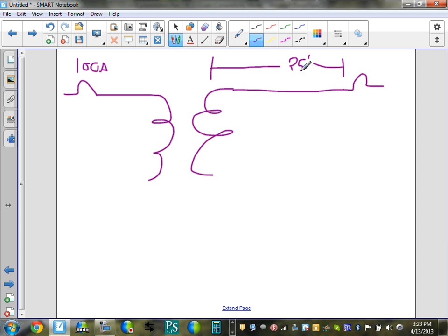The rules are to size it. This conductor is going to be, let's start with 1/3 this time. 1/3 multiplied by the overcurrent protection device, which is 100. Our voltage is the same thing, 480, and 240 on the other side, just to compare what we did. So that will be multiplied by 480 divided by 240, not the other way around.